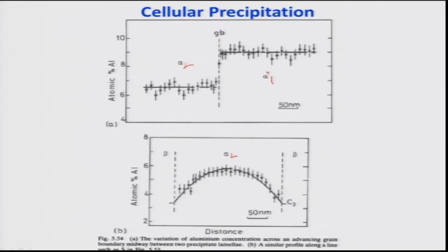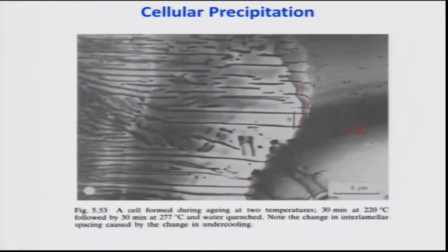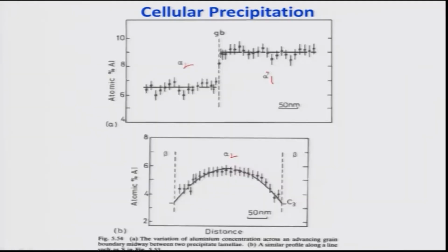Now, this is to be expected, since the precipitation is occurring at a relatively much lower temperature compared to the first mode of phase transformations. Therefore, the solute transport will happen along the boundaries, okay. One can also measure chemical composition, but this tells you that only along the grain boundary diffusion is happening, because this is alpha 1, and this alpha 2 has been produced from alpha 1.